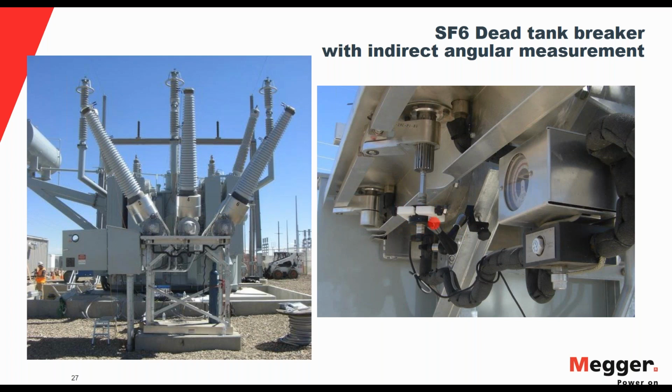And now the transducer, in order to get a correct measurement, we use a coupling adapter and also a coupling bearing to minimize any problems with misalignment, and also a holder arm that holds the transducer and all its weight, so it doesn't hang on the gear itself.